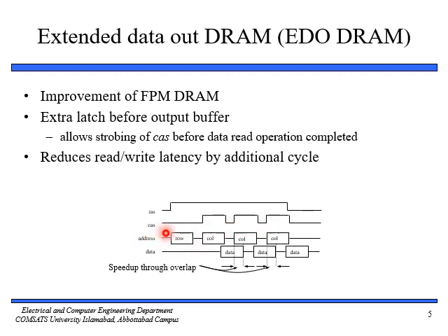At this point, when RAS rises, that is our high clock, we read the row address, and then at each rising of the CAS, we read the column address. Once we have row and column, we start to read or write the data.